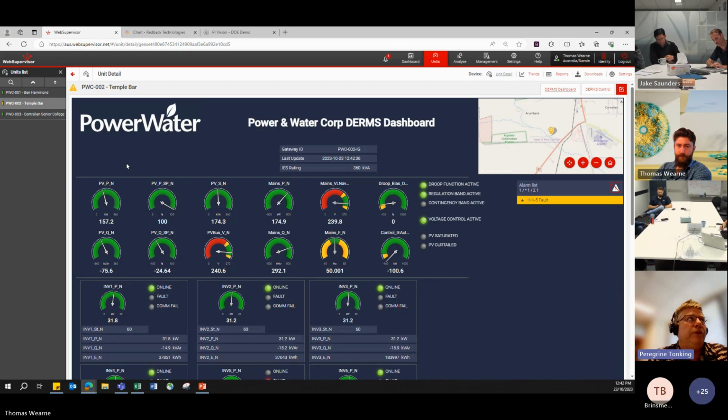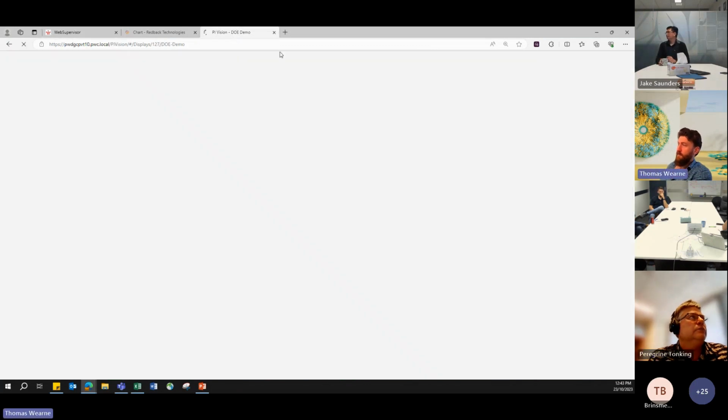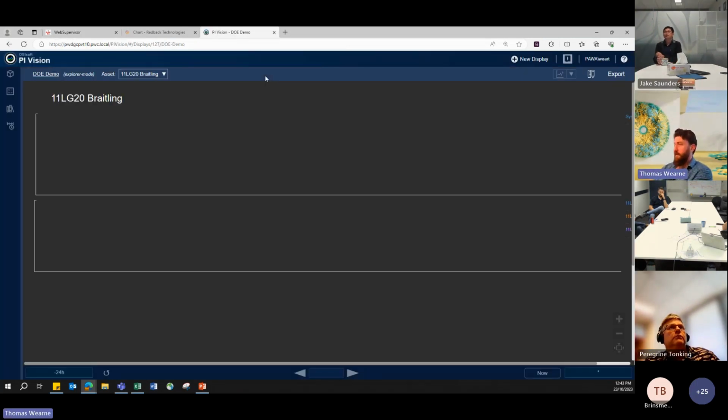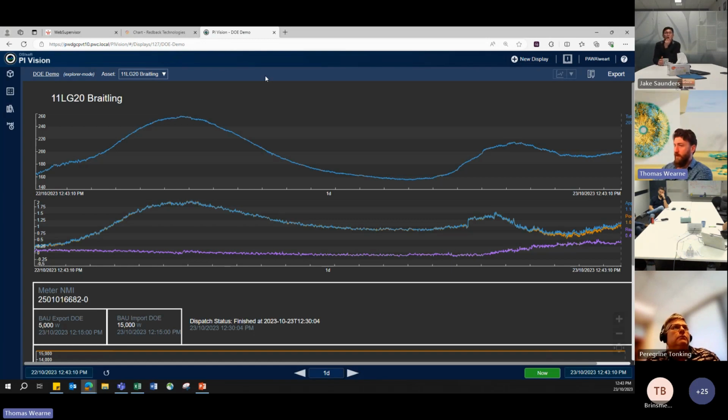Yeah, and in particular in Alice Springs, where you're hitting those system constraints, especially at network minimum conditions, this potentially provides, and if it is relatively affordable, especially down to the granular residential environment, you could be able to better manage PV-rich feeders under minimum demand conditions and offset substantial further investment required on the supply side. Yeah, and that's exactly one of our tests that we've got GridCube working on.